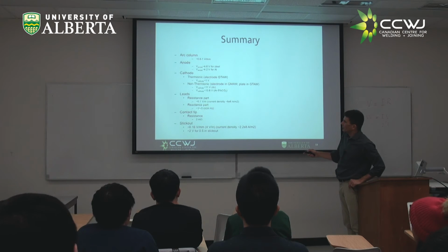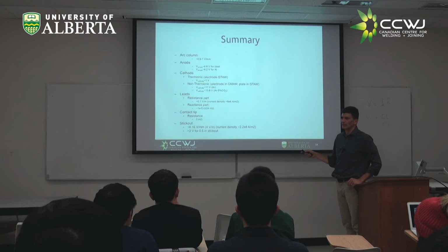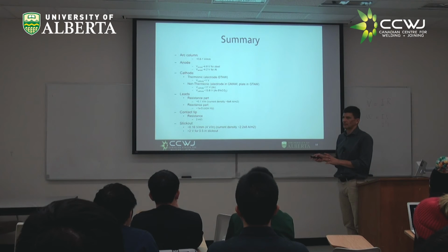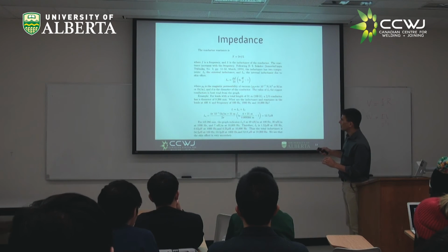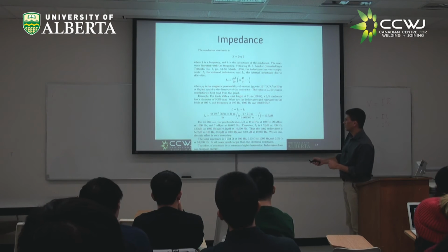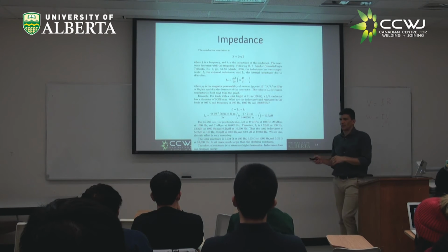So 100 hertz would be 10 to the minus 3, and for 31 meter leads, this would be 0.03, right? This would be 30 milliohms in that case. And if you remember, what we had calculated here was 34 milliohms, doing all the fancy mathematics.